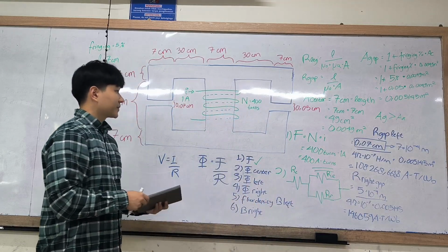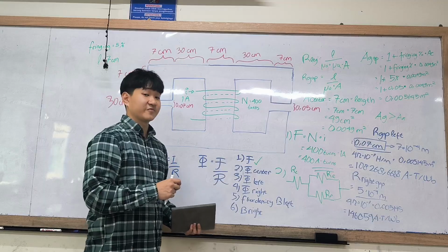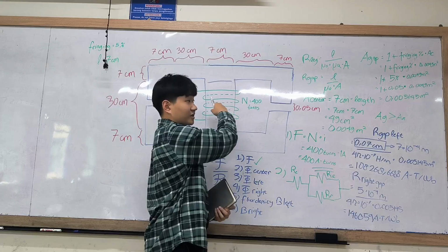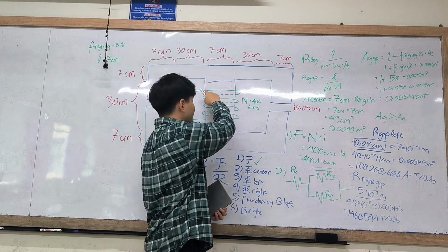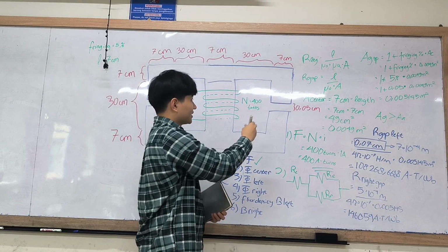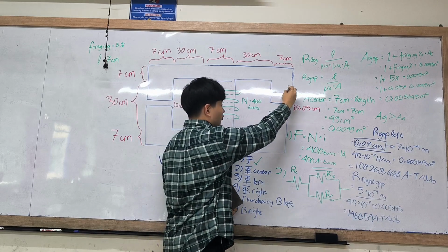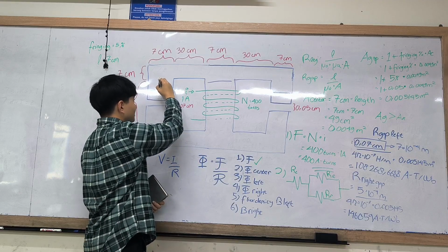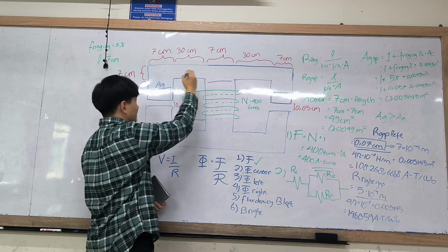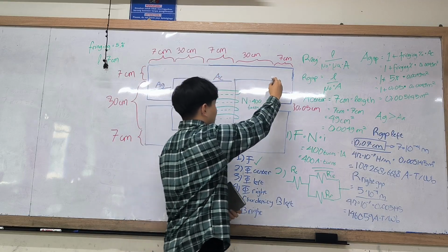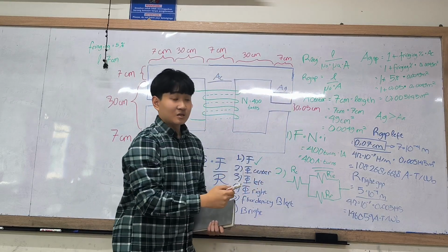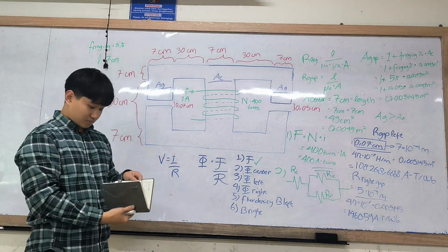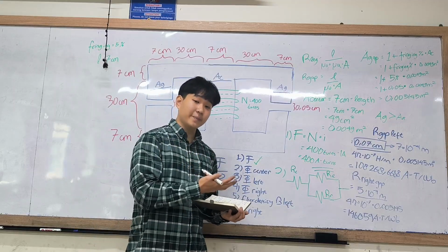And if I have to explain the fringing effect again, basically this is the regular length. This is the regular area for the center part, but the left and the right areas become wider by a small bit. This is area center, and this is area gap. They become bigger due to the hole that is left in between the two legs. So we have found the reluctance of the left gap and the right gap.